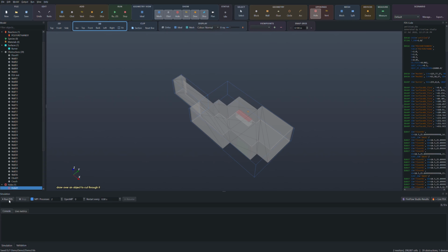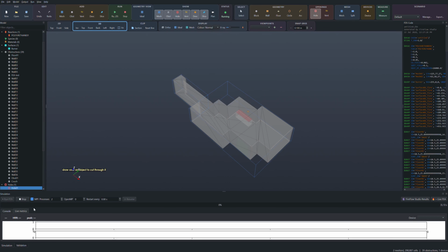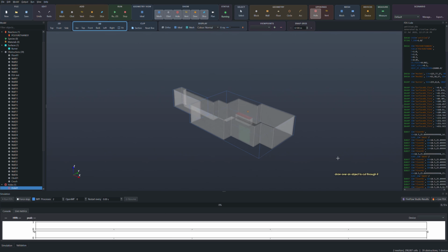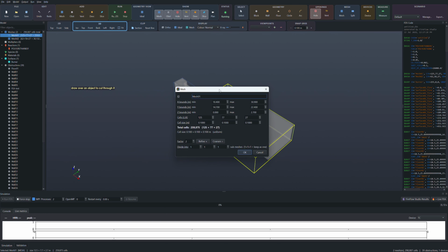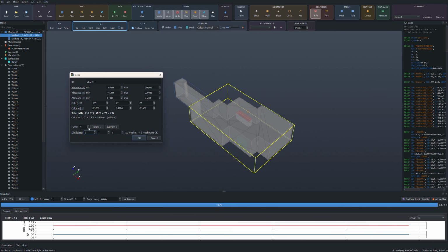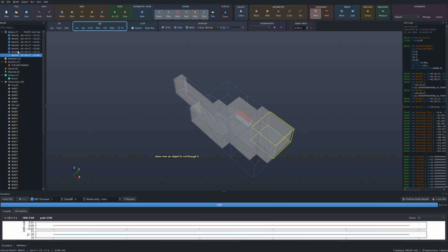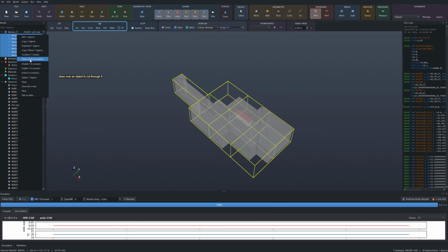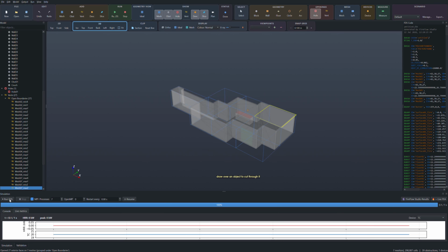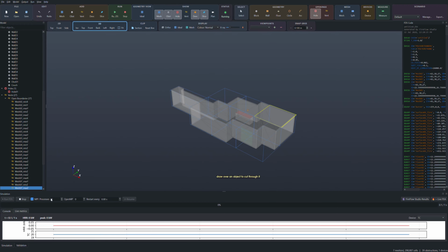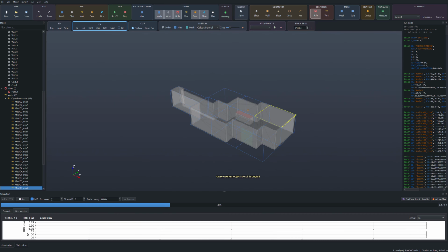Okay, you can then run it straight from here. It's going to automatically detect, oh, you know what? I did not show you one of the best features, and that is if you choose this mesh, you can easily split that. Let's say 3 columns, 2 rows. There we go. And most crucially, open your mesh boundaries. So now, if I say run, it's going to tell me that I already have saved files in there. Let's overwrite it. It's going to pick up how many processes I have.